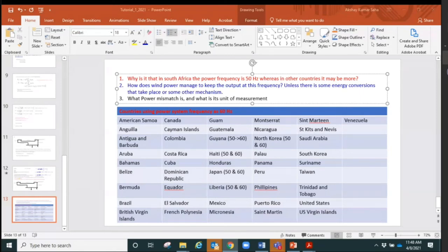Now we can also think that on that same bus some loads are connected, meaning it will have active power consumption and reactive power consumption. We can call them PLI, meaning load of the ith bus, PLI and QLI. Now active power injection is considered for that particular ith bus. So what is active power injection? It is the difference of these two, PGI minus PLI.